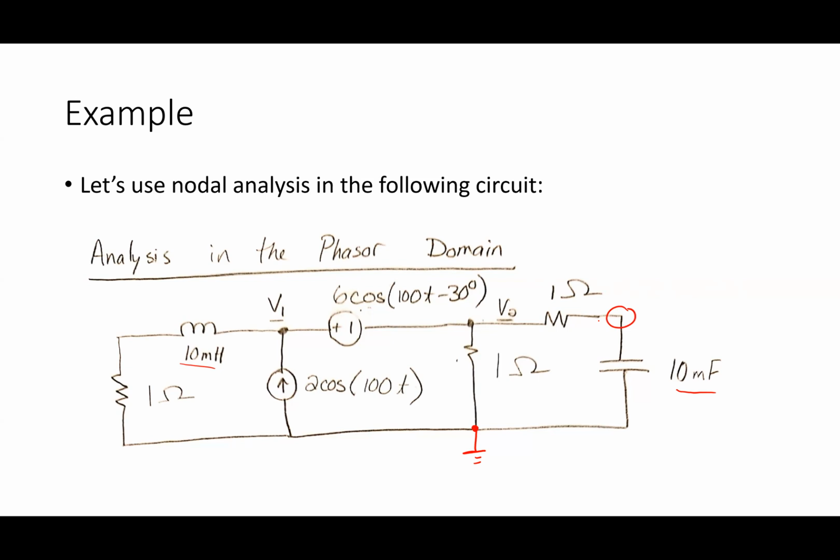It's not really an independent node. I don't know, I should probably know my network theory better and say it probably has some terminology like a subordinate node, or I don't know what it's called, but it's not an independent node that I would solve for, because whatever current I have here and whatever current I have here are the same. So I basically think of the combination of the 1 ohm and the 10 millifarad as one impedance, and I write one KCL equation for that branch.